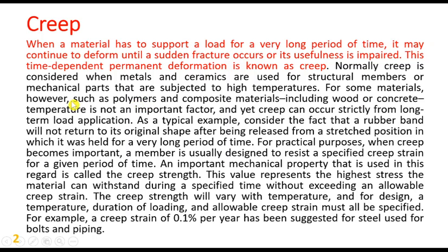For some materials, however, such as polymers and composite materials, including wood and concrete, temperature is not an important factor, and yet creep can occur strictly from long-term load application. For these materials, like polymers and composite materials, creep is just due to long load application. Long term means more time is involved. As a typical example, consider the fact that a rubber band will not return to its original shape after being released from a stretched position in which it was held for a very long period of time.